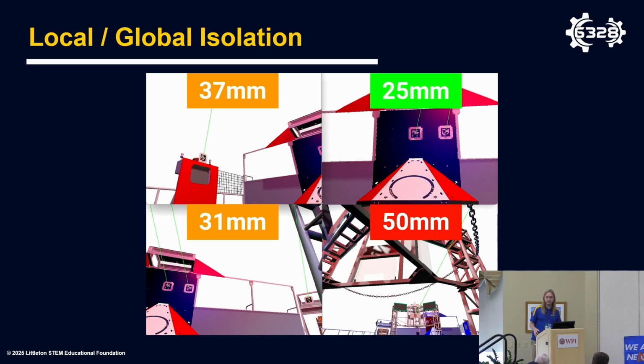In a lot of cases, you can actually implicitly switch between these estimates using a single pose estimator. Here's an example of what I mean. This shows an example frame from our 2024 robot when we're shooting into the speaker. Up at the top, you can see the calculated standard deviations. Lower numbers mean we're trusting that camera more. Most of the time, when we're moving around the field, there's no reason to trust any camera more than any other.